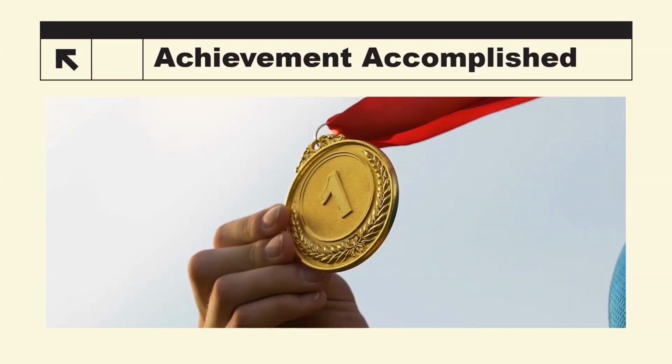And then they just put a number into the software tool to make it say grade 1 because we did the weigh-in method, but they are ignorant of the fact that, hey, you actually have to do math. Some software tools like HouseRater actually have this baked in, to where you actually have to put in the values for each of these things before you even get a grade 1, 2, or obviously in refrigerant, grade 1 or grade 3. Other tools just wait for that final output of whatever that weight deviation value is, and so they're relying on the rater to know to do that math and not just type in a number until you get grade 1.